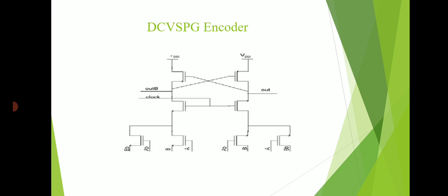This new circuit configuration, the differential cascade voltage switch with pass transistor logic tree, is presented here. In this circuit the pass gate logic tree replaces the NMOS logic gate in the conventional DCVS circuit. This eliminates the floating node problem. It is also related to the CMOS circuit technique, having advantages over conventional NAND or NOR logic in terms of circuit delay, layout density, power dissipation, and logic flexibility.